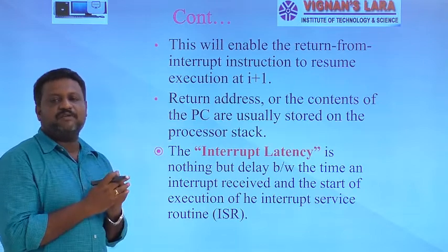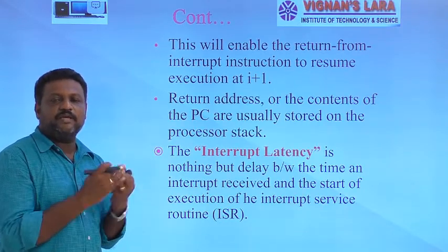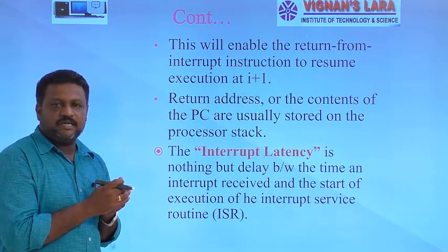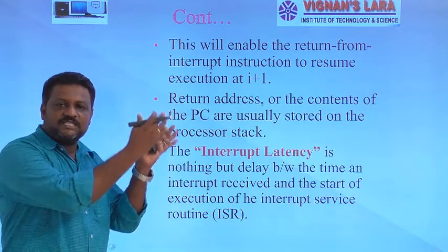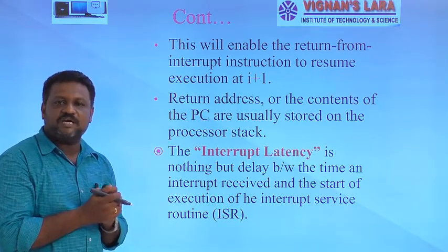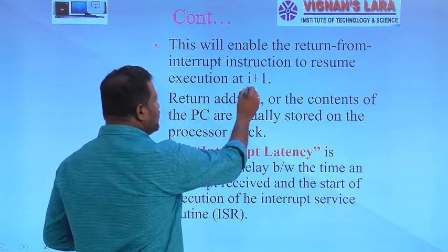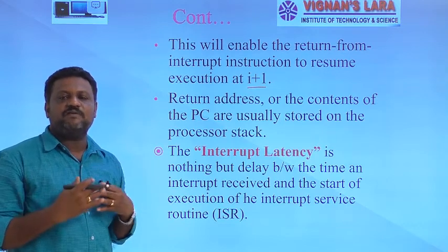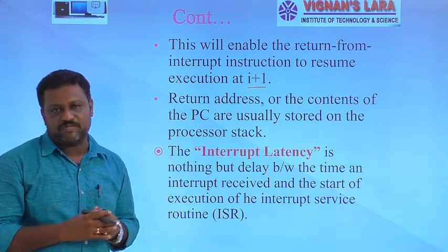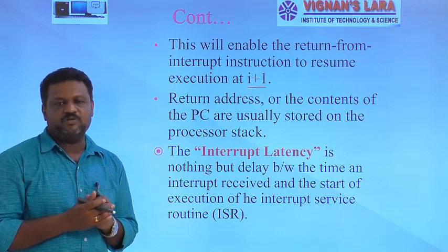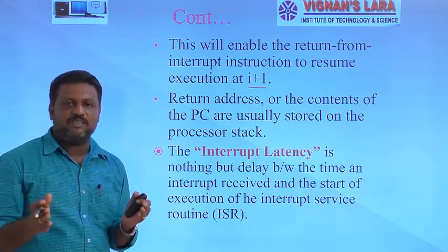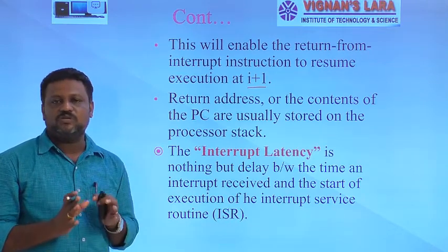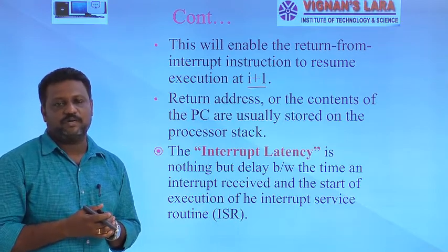Yes, once you come back from the interrupt service routine, again we are moving to our previously stopped program. We stopped at instruction I+1. After successful execution of the interrupt service routine, again we start our execution from instruction I+1. We know this. And one more thing, we know that before shifting our execution from the current executing program to the interrupt service routine, we preserve the PC value. There is no doubt at all. That is in the stack along with the status information as well as some CPU registers which are common to both the interrupt service routine and the current executing program.